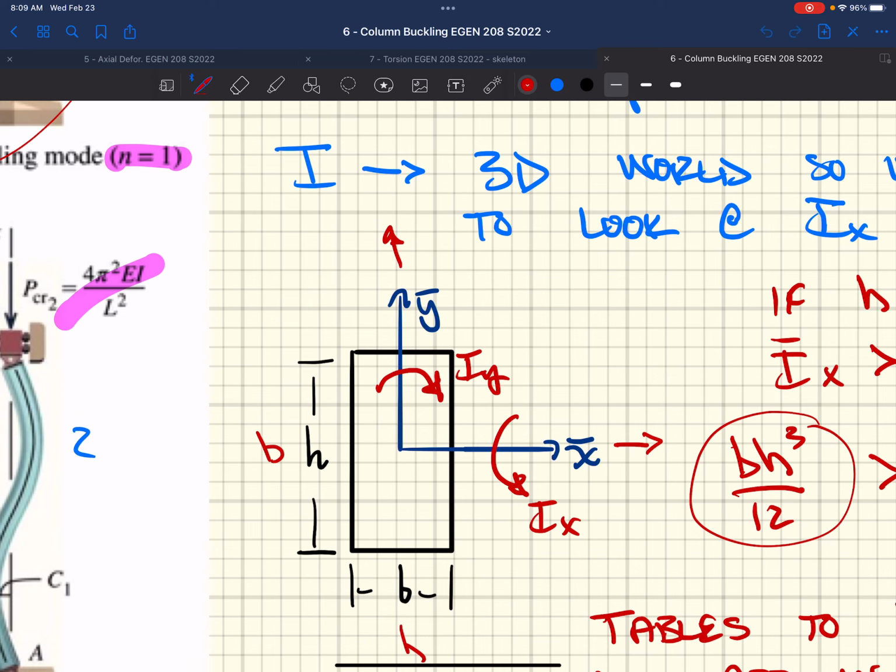So it's fairly detail-oriented with respect to making sure that you are analyzing it appropriately to know, is it buckling in the weak direction? Well, if it's buckling in the weak direction, this thing's rotating about the weak axis. And if it's rotating about the weak axis, this column is going to be buckling along the x-axis. Does that make sense? I tried to find a big yardstick before I came here today, but I couldn't find one, to kind of show you the buckling shapes and stuff like that too, but does that kind of help? Sort of, right?